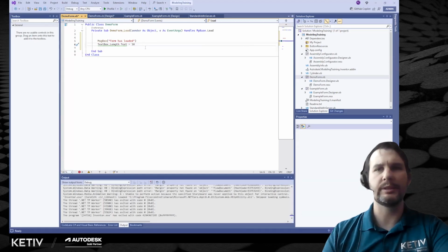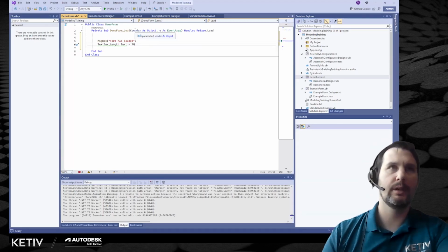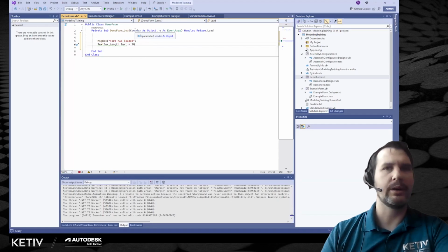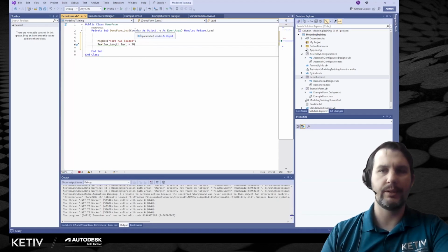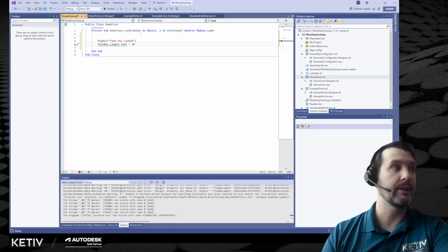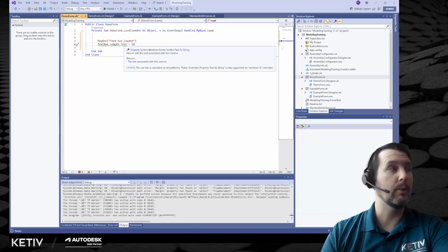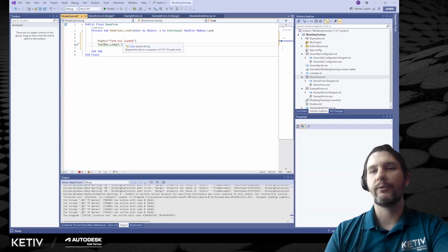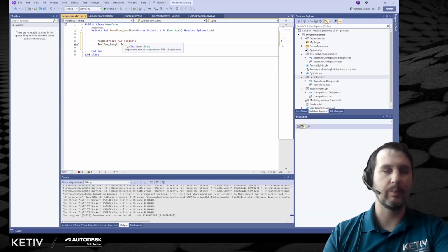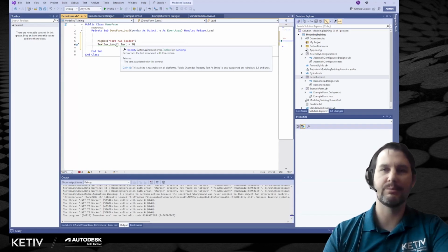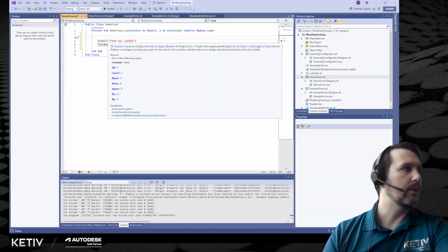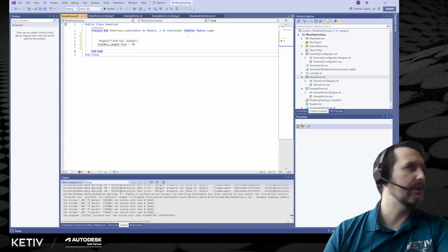So let's say, how would we use this? Let's say we had a whole bunch of options and parameters on our part, and we wanted to load default values based on those or whatnot. We can do math here as the form loads, and then populate default values in text boxes or even combo boxes. I see it often. Combo boxes you need to preload for when the form loads, so it's not just blank. So you'll sometimes see a combo box selected index equals 0, which just selects the first one. I'll go ahead and take this one out. We don't need that. So there's the load handler.